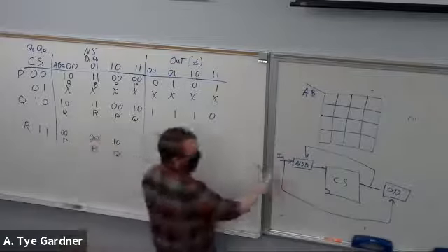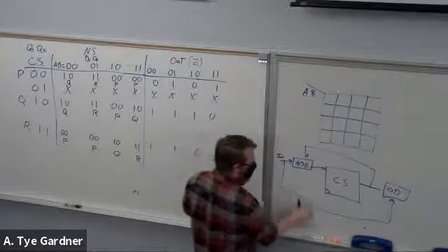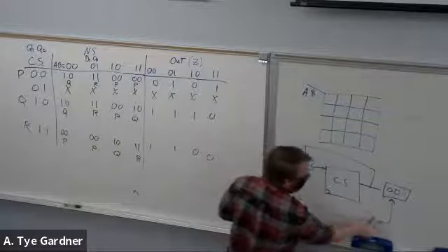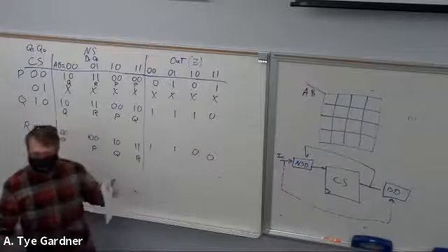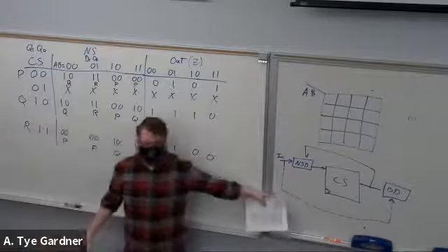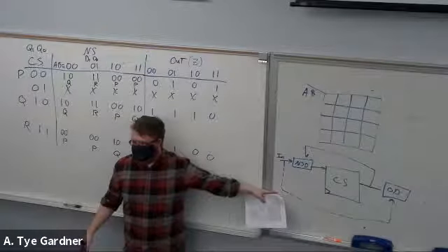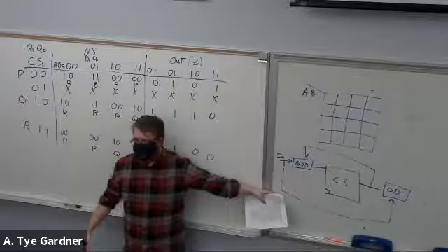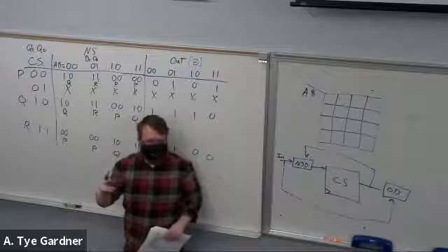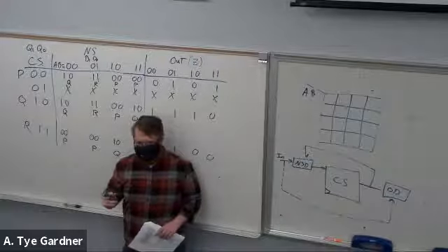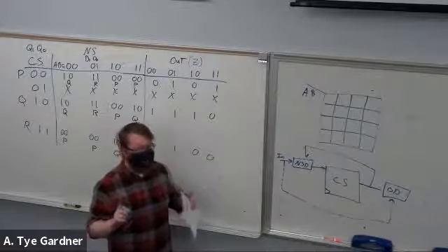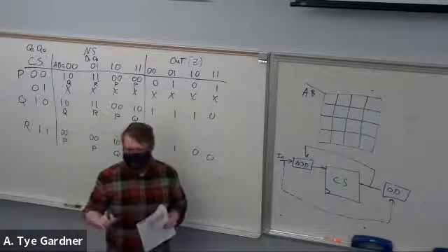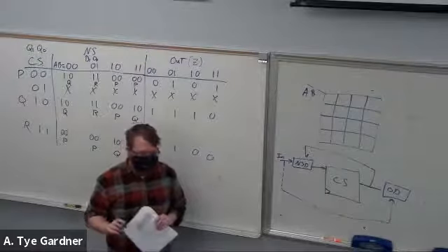Remembering that this one is actually optional. Why is it optional? When do we not use this path? There are two types of state machines, Mealy and Moore. In Mealy, the output cares about both the current state and the input. Moore state machines only care about the current state.